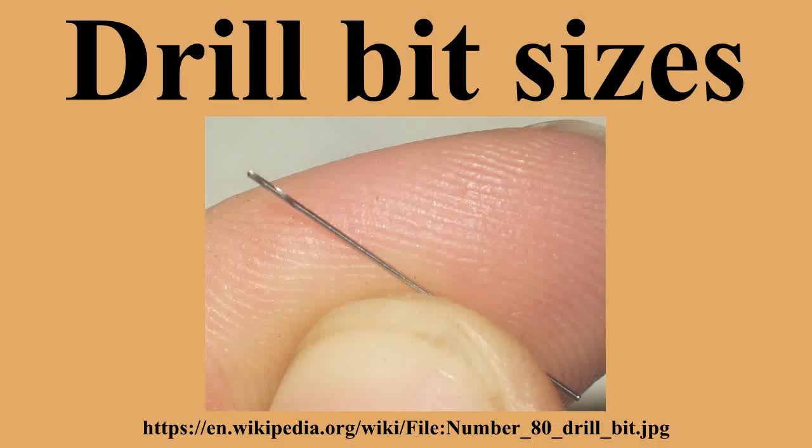From 0.2 through 0.98 mm, sizes are defined as follows, where n is an integer from 2 through 9: n × 0.1 mm, n × 0.1 plus 0.02 mm, n × 0.1 plus 0.05 mm, n × 0.1 plus 0.08 mm.